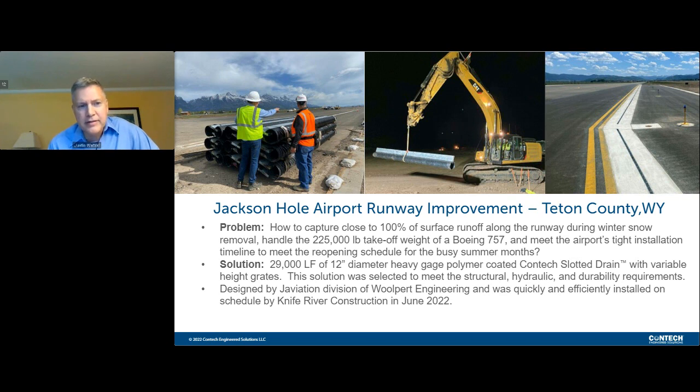Slotted drain is something that has a number of advantages over a traditional design, such as a concrete trench drain. For example, there's no iron grates that can crack over time or have the bolts work loose and potentially flip up and cause a protrusion for aircraft.